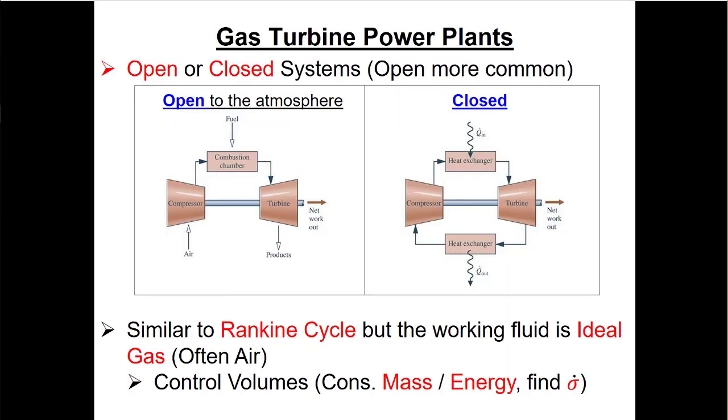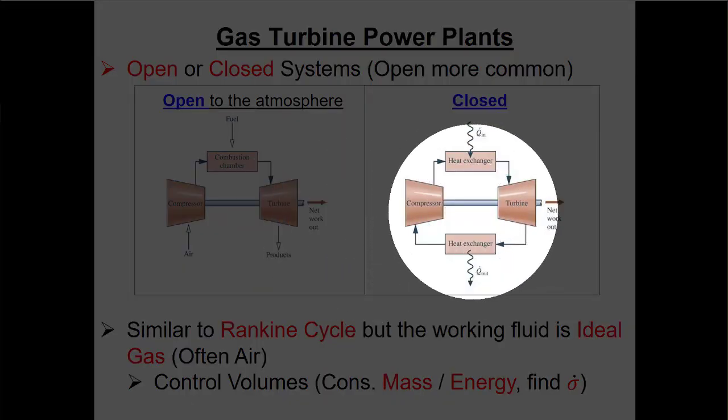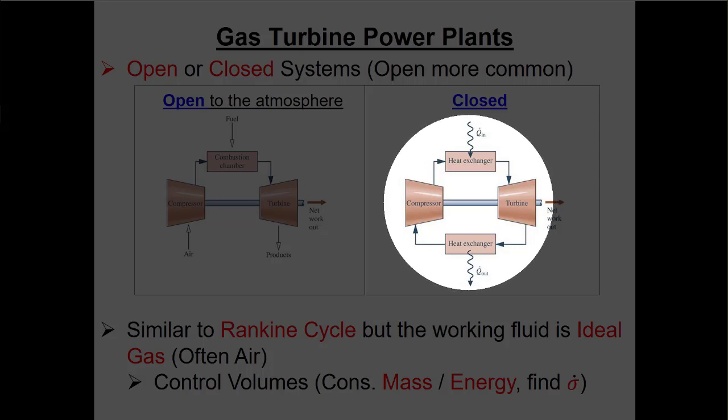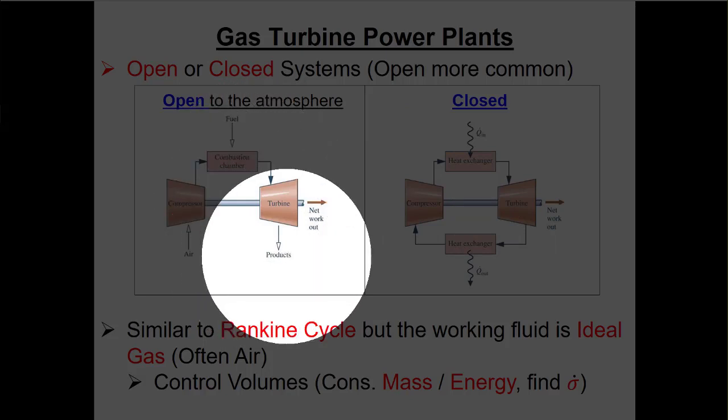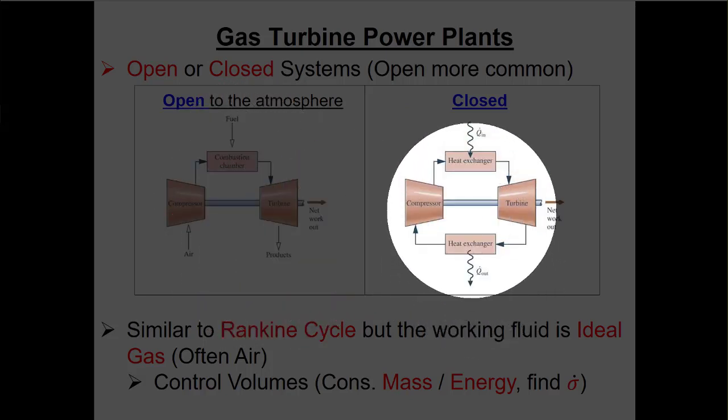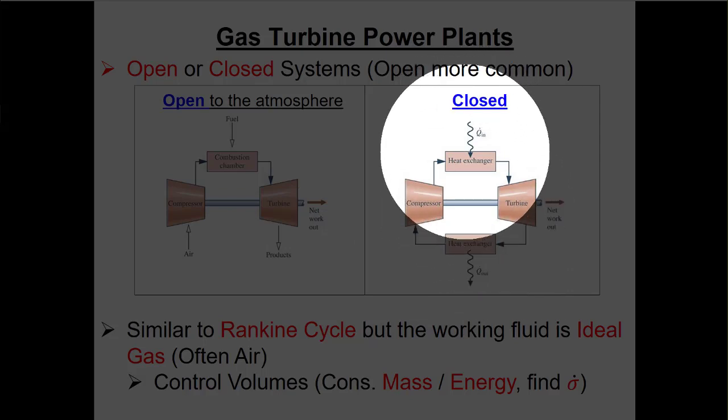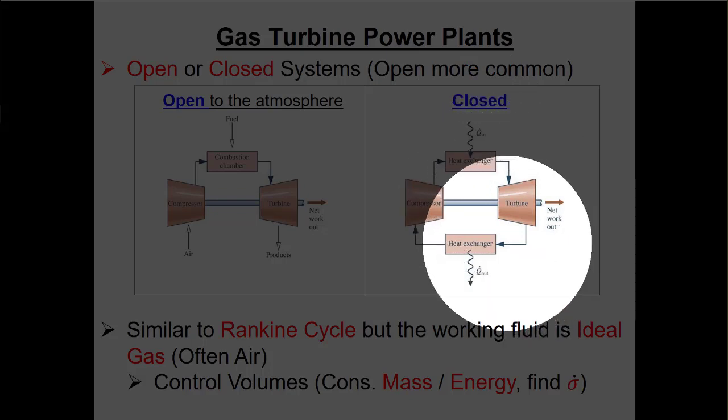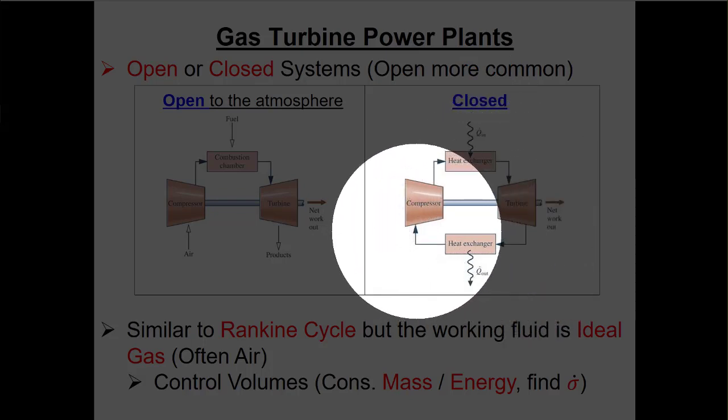So this is when we talked about how a power plant like this actually does have emissions, even though the emissions are lower than they are with coal. Right? Now, sometimes we'll model it as a closed system, and I suppose in reality there may be actual systems that run like this. But here, this is assuming that we just have air and we're not doing any combustion. So instead of having combustion and then exhaust to the atmosphere, we have air that's running around in this cycle, and we're adding heat up here instead of burning something, right? And then we go through the turbine.